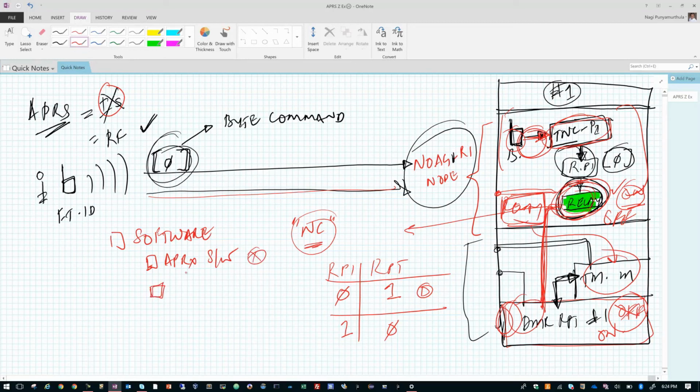The other option is that I could go direct to the AX.25 protocol, which is far closer to the hardware. By that, I can have the Raspberry Pi easily unpack the AX.25 packet, decipher the command, and process it. So it's fairly straightforward to work directly off of the AX.25 pipe and get the work done that way also.